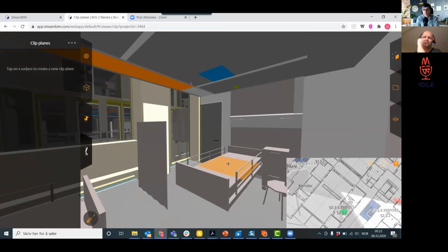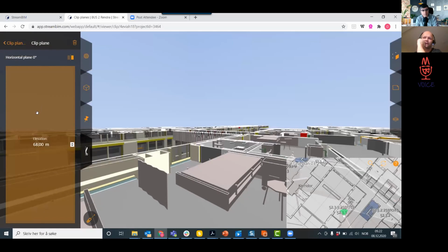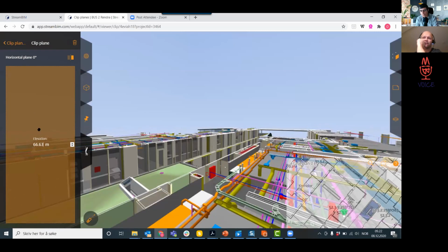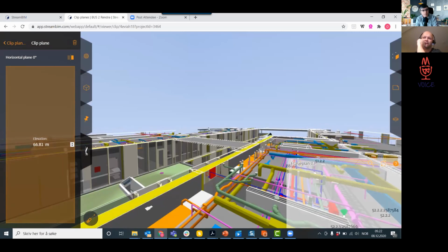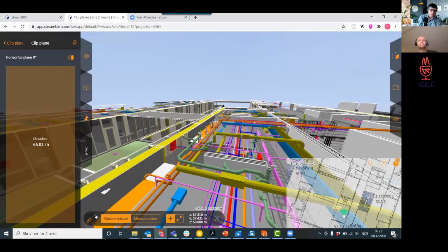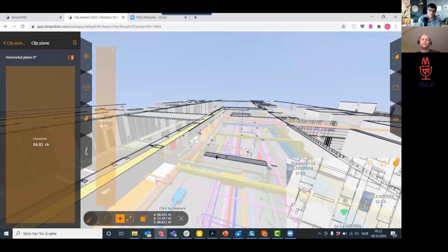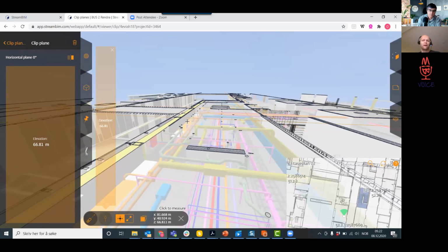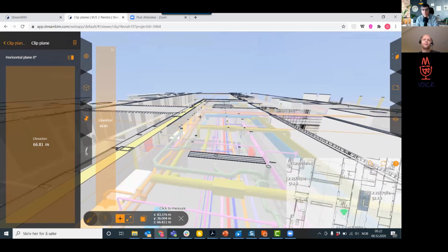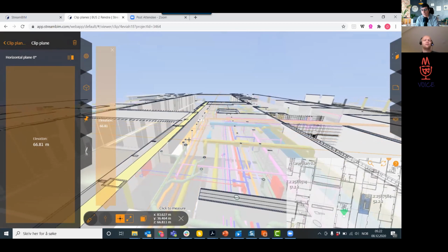If we set a clip plane here, and maybe drag it down to the next level here. Basically, if we add a measure plane, if you want to measure whatever, this is where we produce a drawing right out of the model. Then you needed an additional one. So first, a perfect cube, 6 different clip planes, but then you wanted to measure as well, and then you needed the 7th and maybe the 8th. So that's the reason.